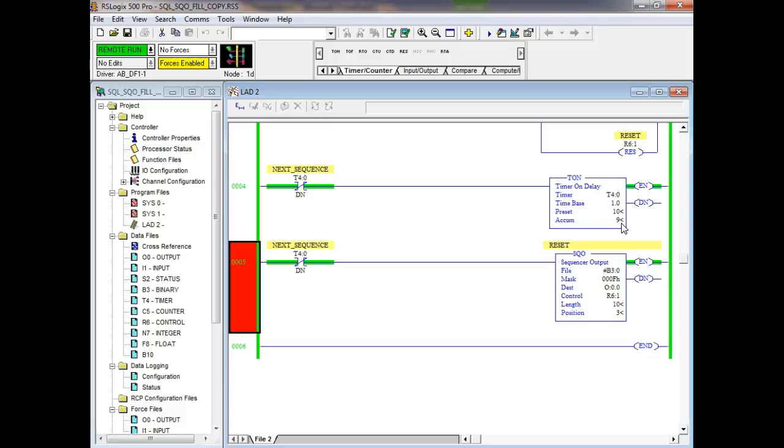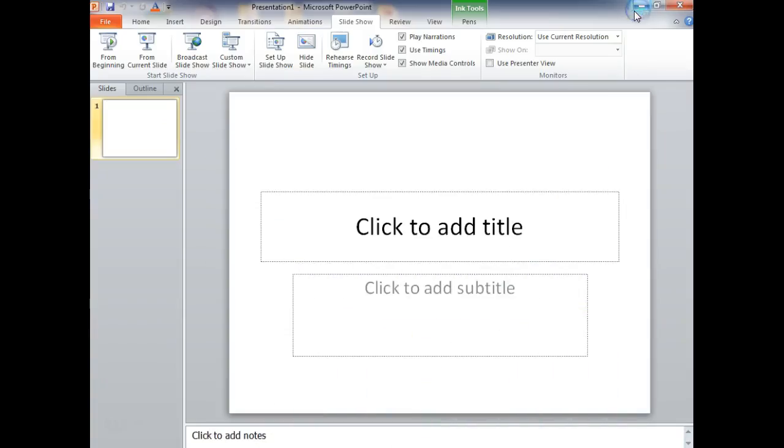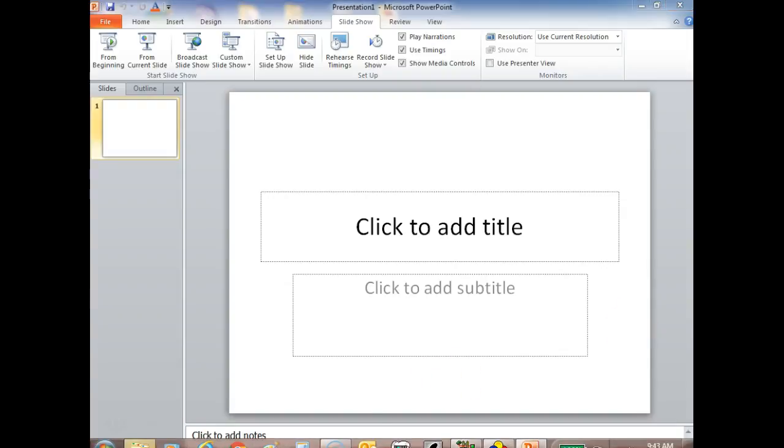So when you look at the outputs, every output has a common. That's why they're limited with the number of outputs they can put, because they're trying to do it on the same side of the terminal block that they're doing our inputs. Our inputs use 2 commons, and they go in groups for this PLC. And the MicroLogix 1000 is the same. The MicroLogix 1000, which some of y'all are doing, has relay outputs on it. And that's why you can actually hear those little relays clicking.